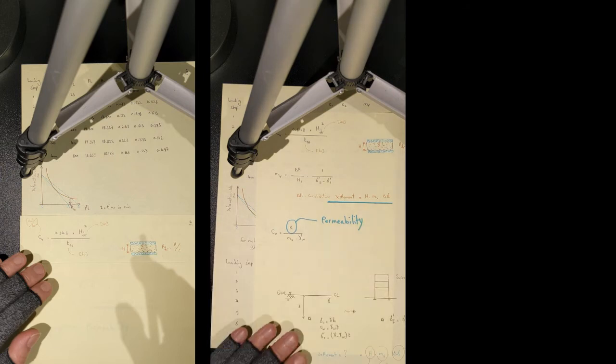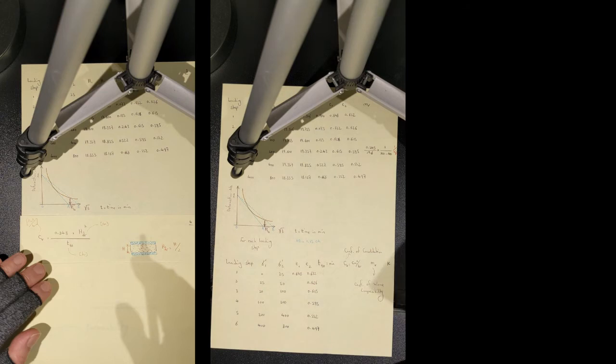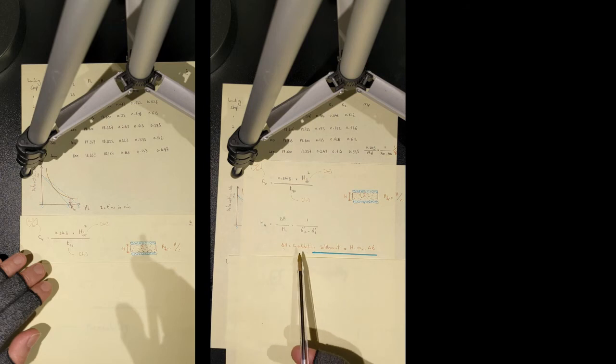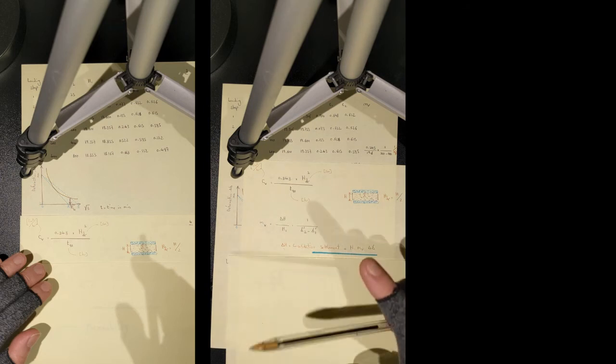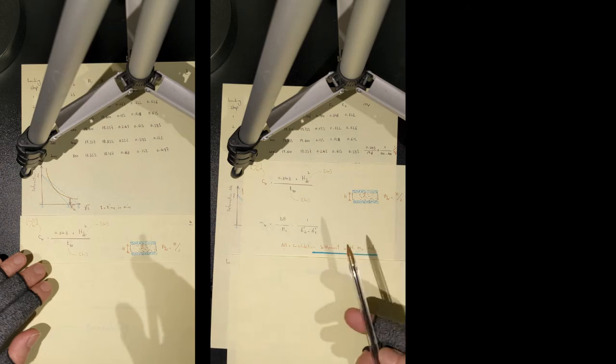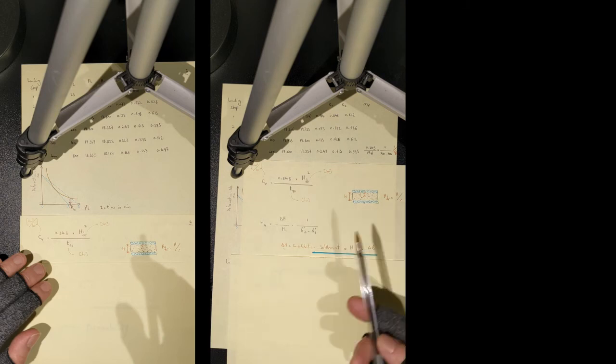Now let me ask you a question. Well, this seems to be a very useful equation to measure the consolidation settlement beneath foundations. Consolidation settlement beneath the foundation is equal to H, that is thickness of your clay soil, which is fully saturated, or you assume it to be fully saturated beneath the foundation, multiplied by delta sigma, will be the surcharge or the effect of surcharge on your clay soil, multiplied by M sub V. It seems a very, very simple equation.